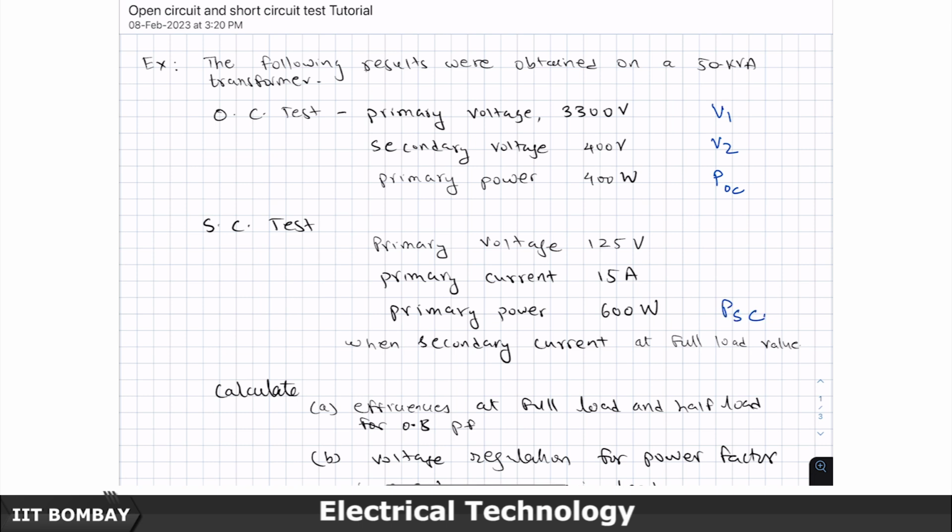The no load current is also negligible, because the flux is much smaller. The no load current is only a few percent of the full load value, and now the flux developed is 1/20th of that. So, if the no load current is, let us say, 2%, 1/20th of that will be like 0.1%.